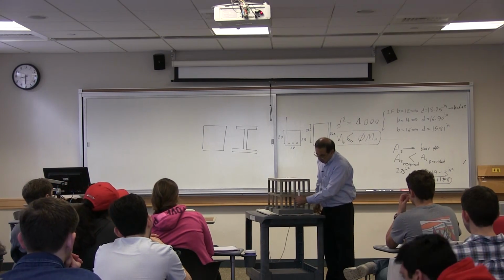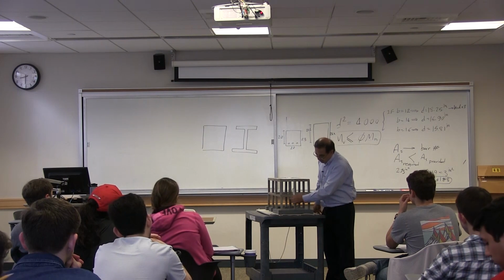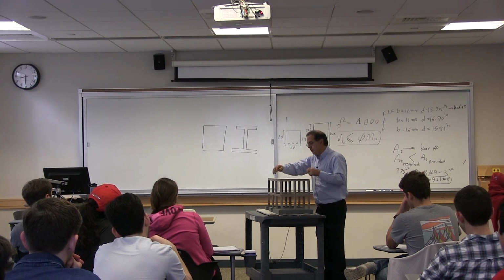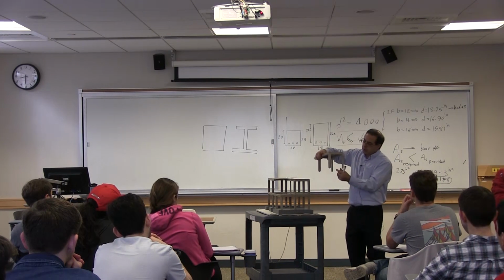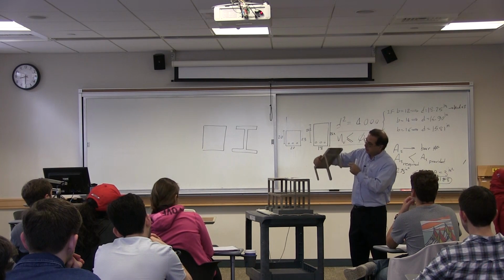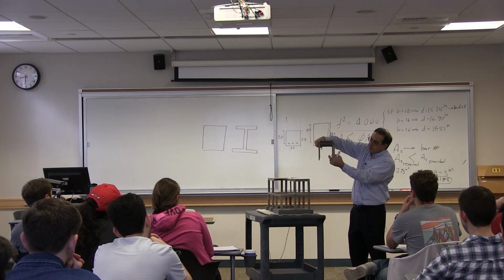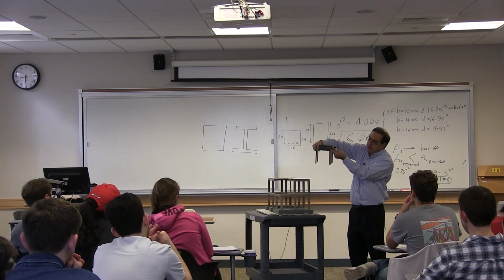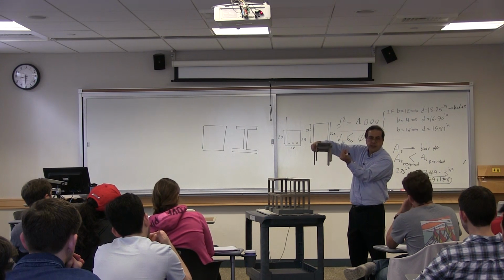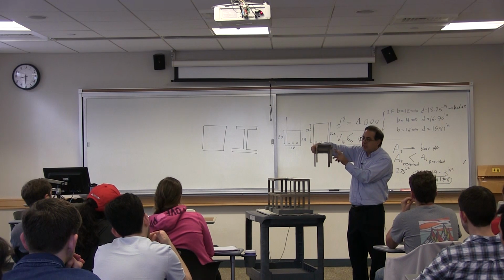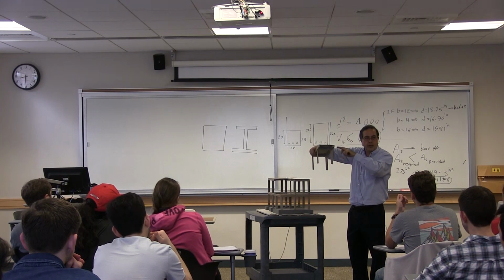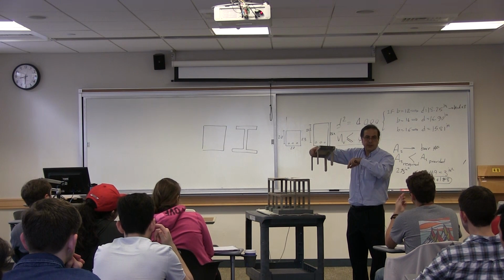The column goes up, and then the beam, let me show you here. The column goes up maybe from this direction. The column is going up, and the beam is going to be narrower than the column. When the beam is narrower than the column, making the formwork around that joint is very complex.